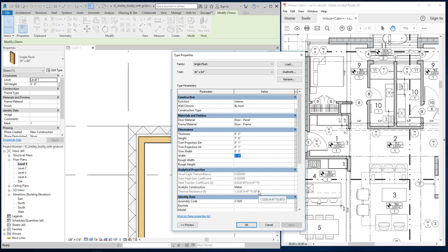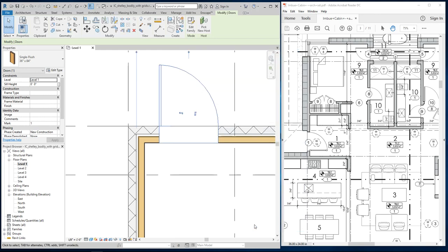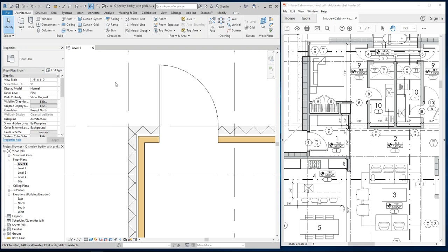If I make a change to this door within the Type Properties dialog box here, so if I change it to like 5 foot wide, any door with this exact same name will have that change made to it. Even though the name didn't change, right? Any door with that name will have that change made to it. It's like a block, okay? Everybody's smiling like, it's wonderful. It's wonderful. Okay, I'm going to hit undo on that real quick.